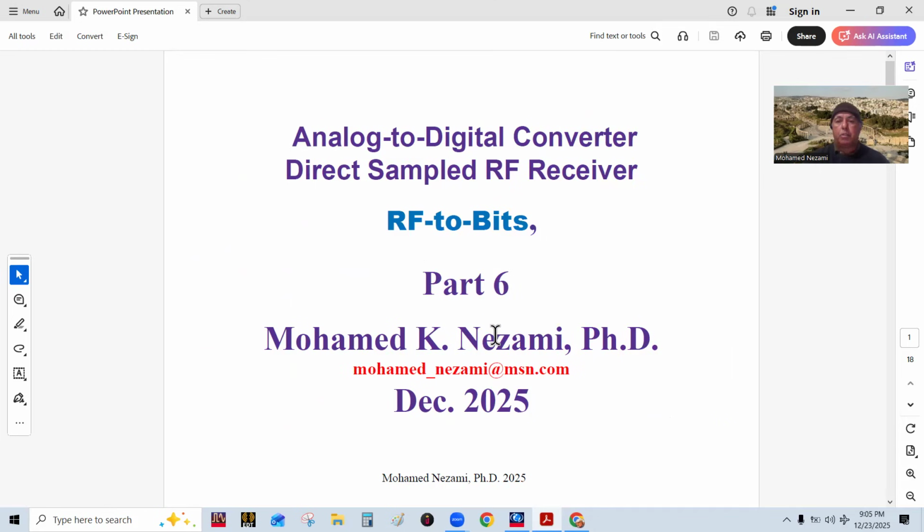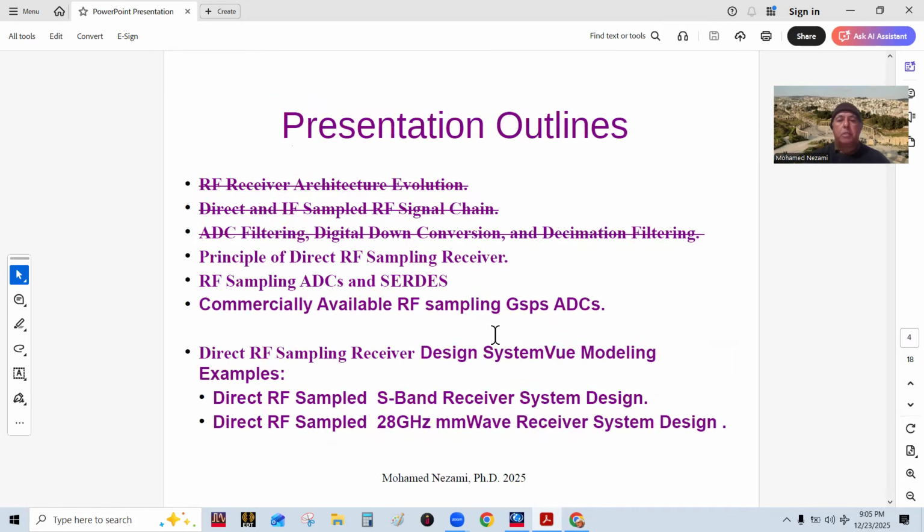That's really the trend, and it's starting to be feasible because several companies right now, Texas Instruments, Analog Devices, Teledyne or E2V, have all brought out tens of gigasamples per second devices that integrate part of the standard digital signal processing blocks like digital down converters and decimation filtering and so on.